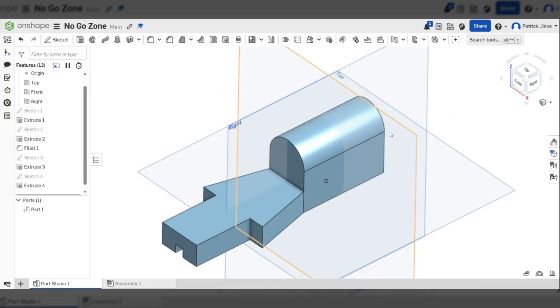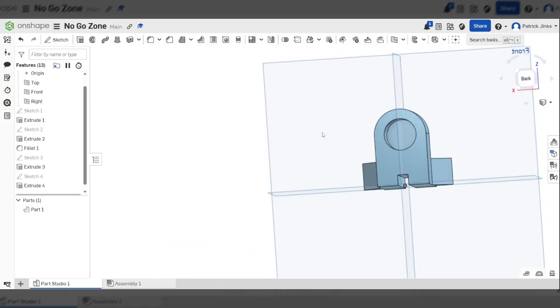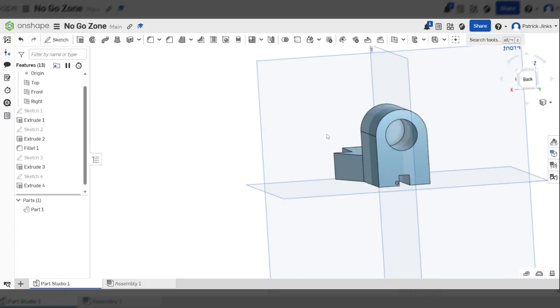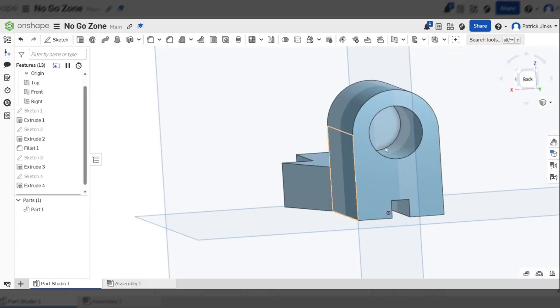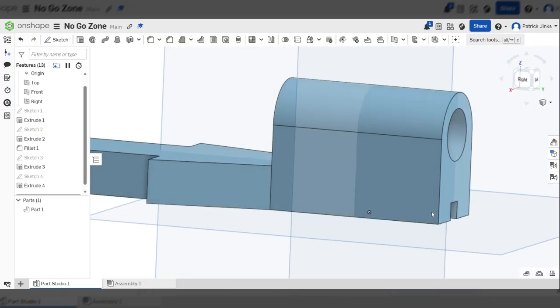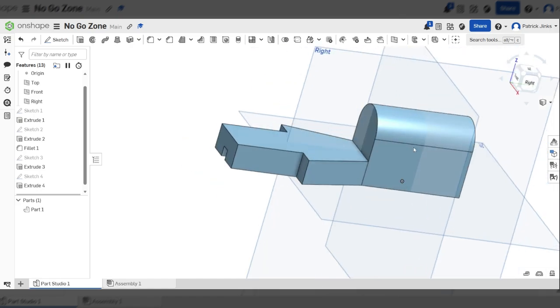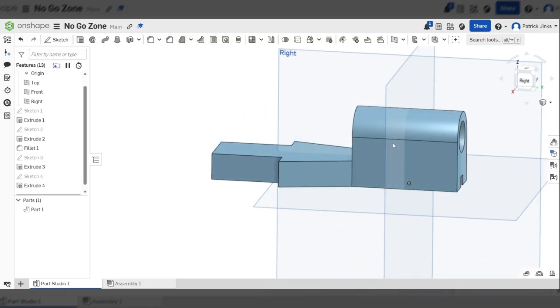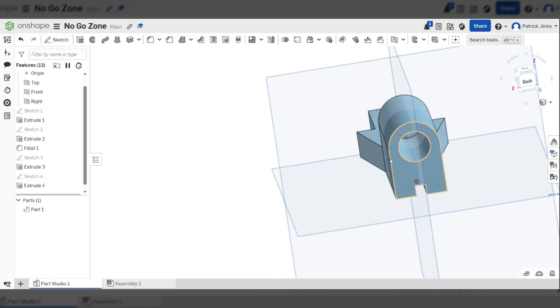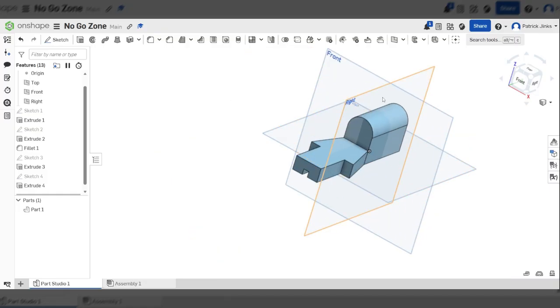The one thing I will say as I leave you, when designing your car, and we'll get to this and you'll see what I mean, you will probably put extrudes through both these grooves we've just cut. So you'll put material through this just in the way OnShape works. It won't reserve this shape for you. It won't hold the shape. If you put an extrude through the car, if you put a profile through there, it will just fill these gaps out. And we are going to be doing a fair bit of that. Don't worry, the last thing we're going to do with the car is recut those. So if you go into those areas, don't worry, we're going to make sure at the end we cut those out.